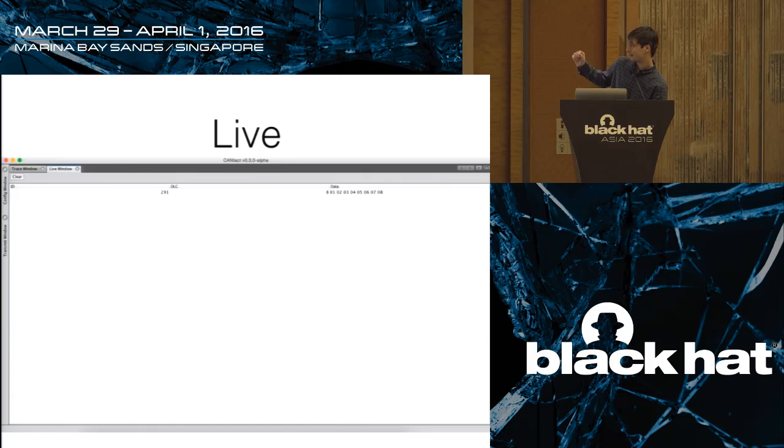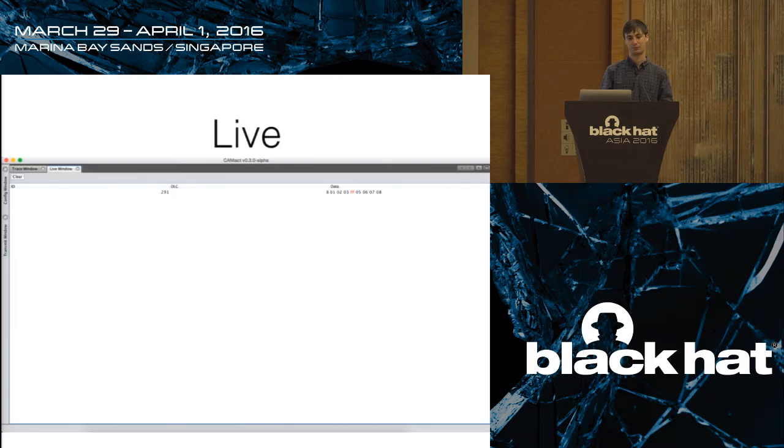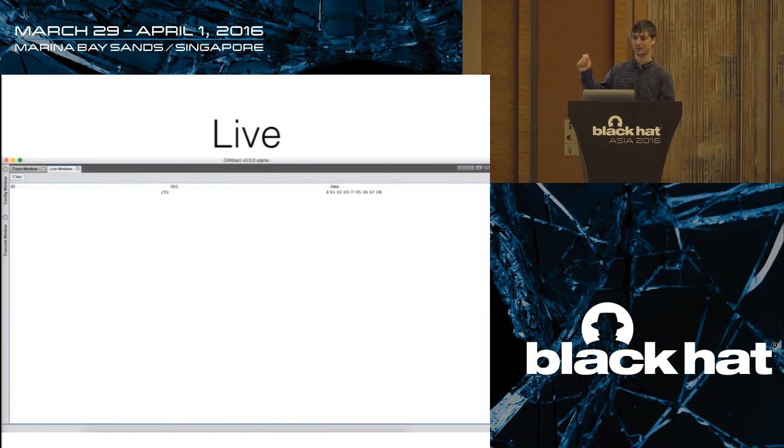This live view, very simply, shows you one row per CAN ID. What changes is the data. As that data changes, and this is a simple example, it gets highlighted in red, which might be a little hard to see on this slide, but as a byte changes, it literally changes color. This lets you look at like 100 different CAN messages at once and see certain things changing. You do something to the system, be it revving up the engine, stomping on the brakes, opening the sunroof, or changing your position for GPS, and whatever's turning red is what's changing.